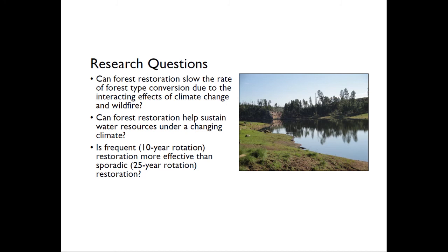One of the negative potential effects of vegetation type changes is that if you replace ponderosa pine with juniper, it doesn't accumulate snow as well. It has a higher potential transpiration rate, so you actually get less runoff from a pinyon juniper forest under the same precipitation as from a ponderosa forest.